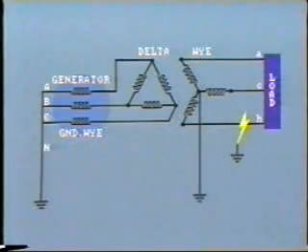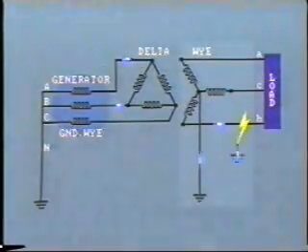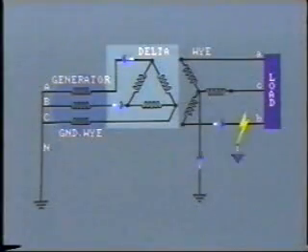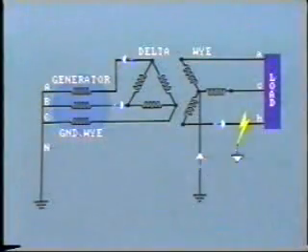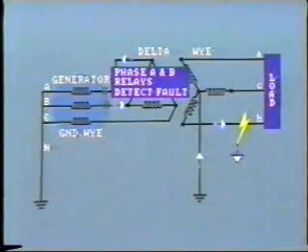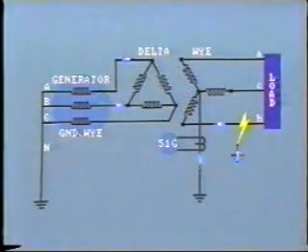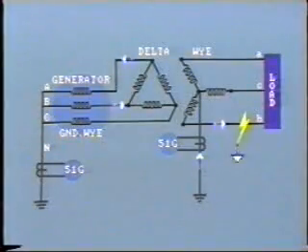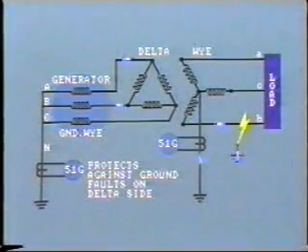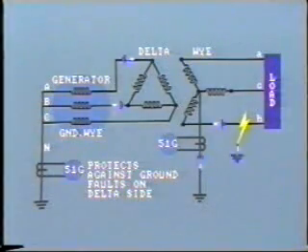With the Y side grounded, ground fault current would flow in the faulted phase of the Y winding and would be transformed into the delta winding as shown. Note that the phase to ground fault on the Y side manifests itself as a phase-to-phase fault from the delta side. Thus, generator phase A and phase B relays could detect the fault, as could an overcurrent relay in the neutral of the transformer. An overcurrent relay in the neutral of the generator would protect against ground faults on the delta side of the transformer.